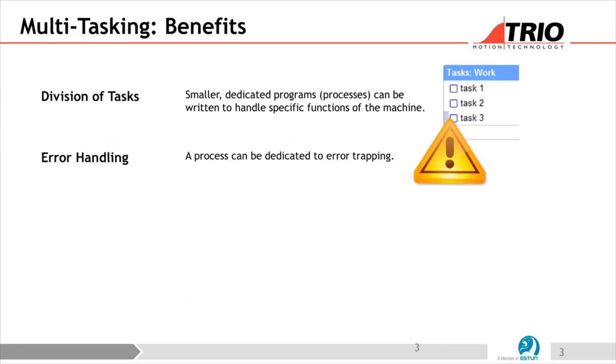into something that's fairly specific. Even if you have a large machine, you might have an input side of it which maybe has 3 motors working together. That could be defined as a task that's running the input side, and a middle bit of the machine with a certain number of motors, and an output part of the machine with a certain number of motors. And you might well split it up so that one program runs the input side, one program runs the main bit in the middle, and another program runs the output side. But it's all down to particular machines, really.